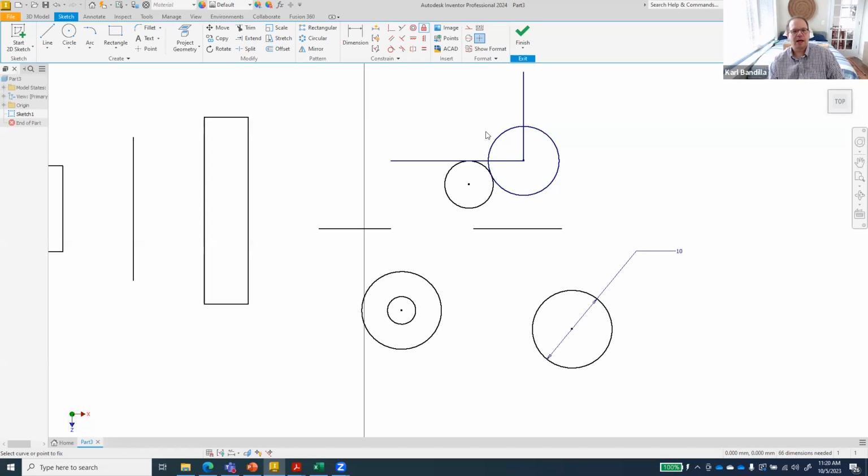All right, let's try some other stuff. And that is the other set. We already talked about trim, extend, and split, but maybe we can just do that one more time. While all of our lines are nice and straight now, so that's not very helpful. Let's do a line right there, for instance.